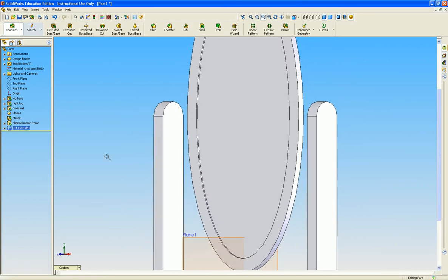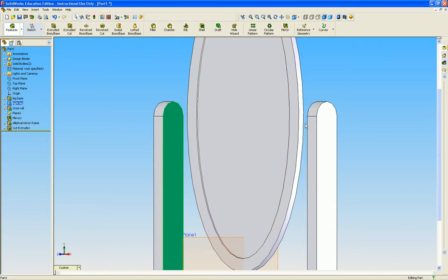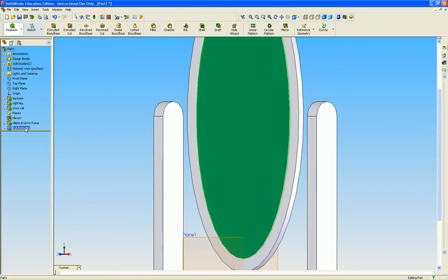Our last little step there is we're going to put the pins joining the mirror there and there. And before we do that, we'll rename our cut extrude here to be glass mirror. So we will click on it, F2 and glass mirror.